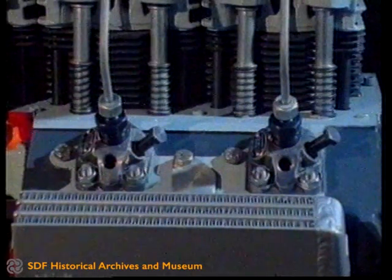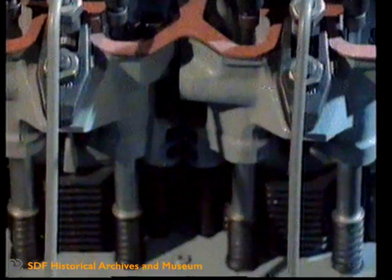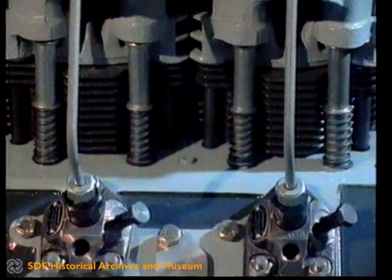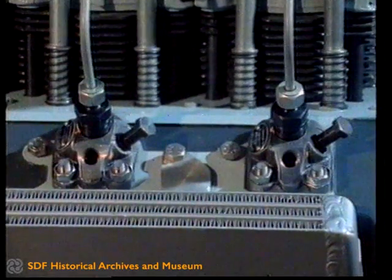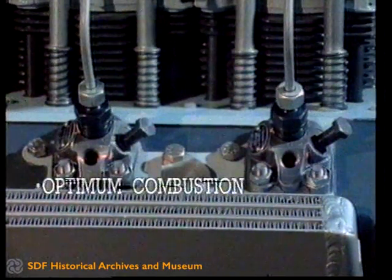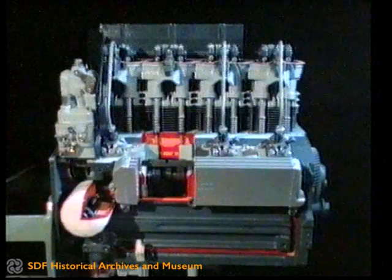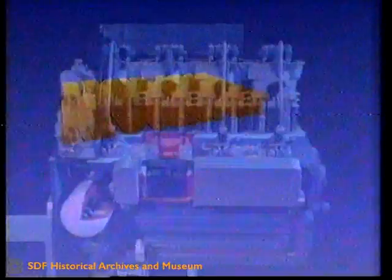Very short, equal length injection pipes. The adoption of very short pipes markedly reduces the pressure waves, similar to water hammering, which can form by the effect of the extremely rapid sequence of fuel delivery under very high pressures, and which can make combustion irregular. Optimum combustion, greatly reduced consumption. The equal length of the pipes guarantees uniformity of fuel feed to all the cylinders.